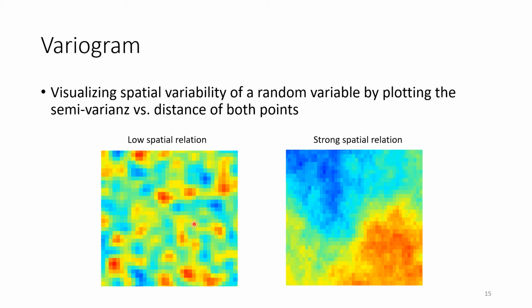so your macroscopic dispersion is much higher. So if you want to model soil transport, it really won't matter so much if this low conductive point is over here, or over here, or the other way around, because the dispersion simply takes place based on those small scale high contrasts in hydraulic conductivity.